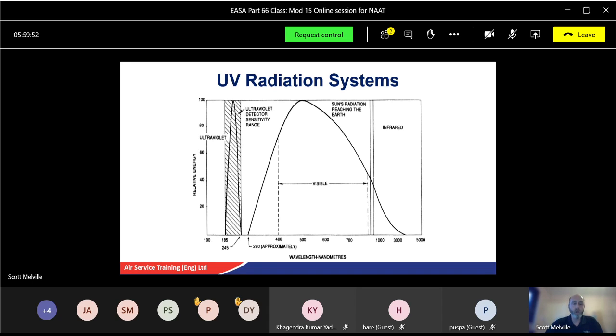They have been used in some military aircraft, such as the F-111s, the next generation, to give an automatic BITE capability, built-in test equipment, to check that it's okay. The majority of UV cells in recent years have been fitted to reheat monitoring systems, and we'll speak about these later on. Certainly the ones I used on the RB199 engine on the Tornado aircraft used pyrometers to check the temperature of the turbine blades, because we can use the heat coming off those as well. Again, we'll speak about more of those later on.